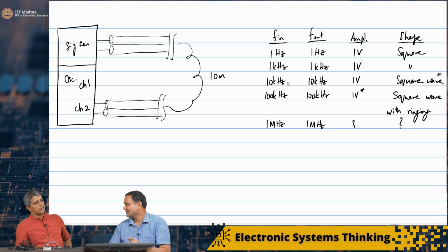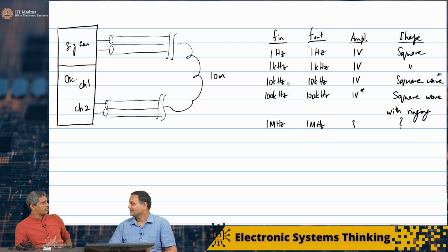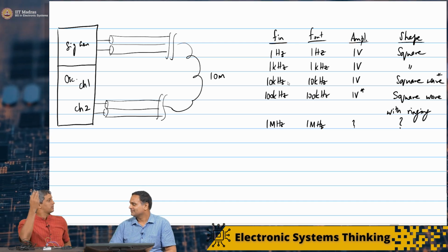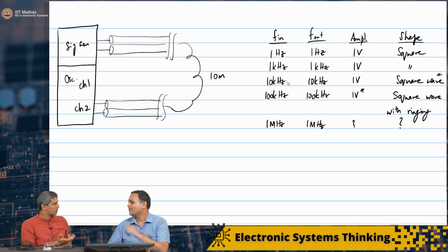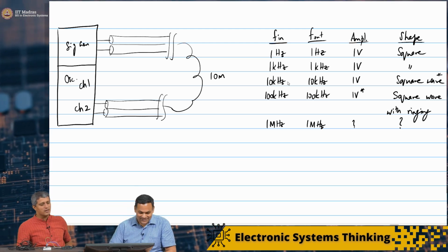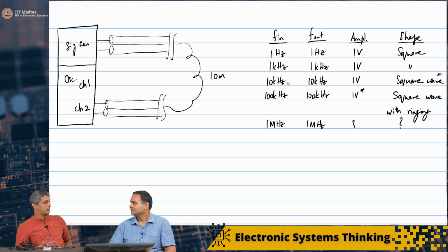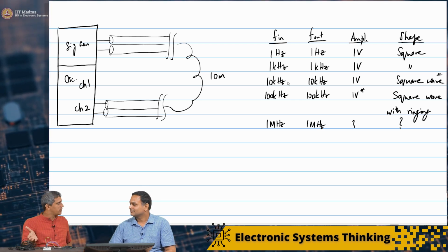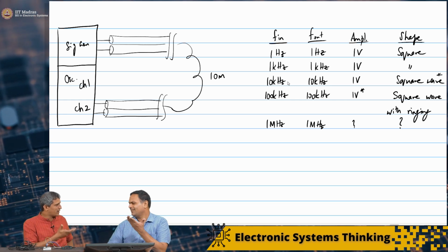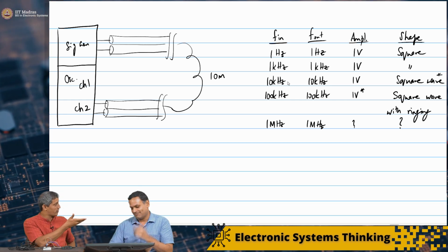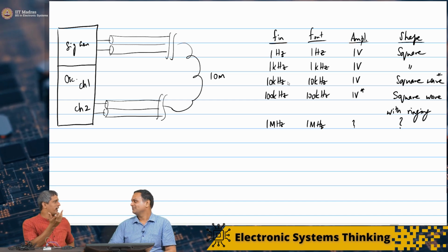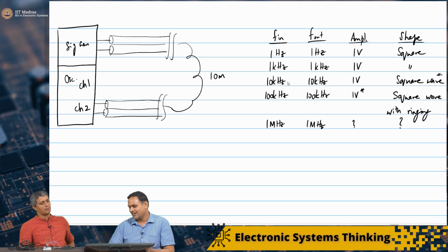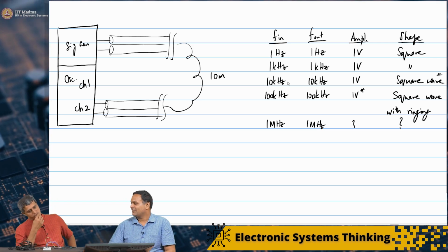So it seems like our cable TVs use coaxial cables, which can receive much higher data rates, hundreds of megahertz. That's right, that's a great way of transmitting. But for the telephone, I think this is okay because the frequency content there is voice. We go back to our discussion on voice. A sampling rate of 8 kilohertz and all is okay. So maybe this is fine for this purpose, to just send the information across the room.